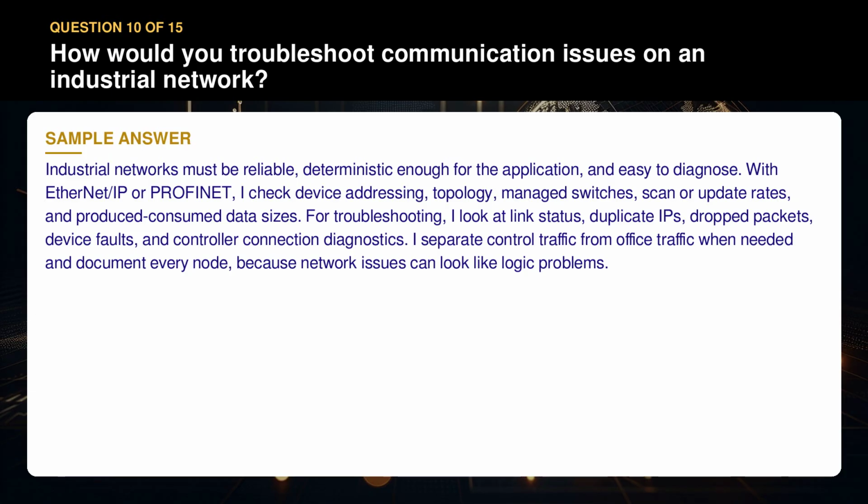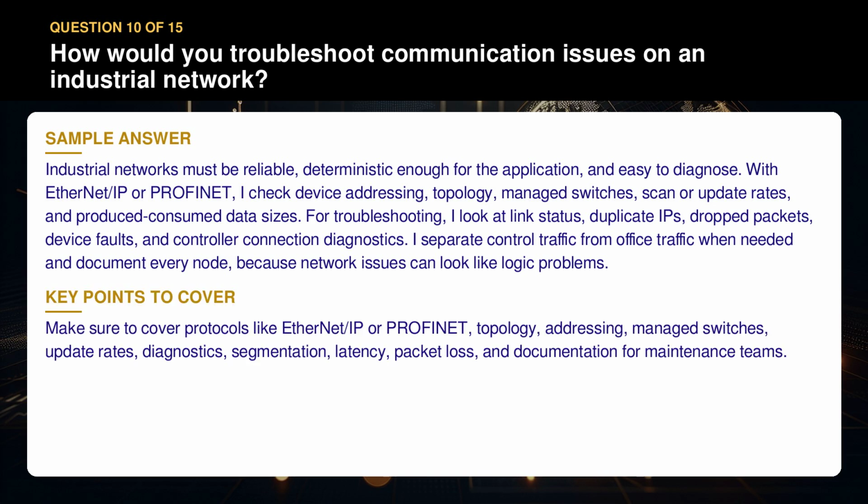I separate control traffic from office traffic when needed, and document every node, because network issues can look like logic problems. Make sure to cover protocols like Ethernet IP or Profinet, topology, addressing, managed switches, update rates, diagnostics, segmentation, latency, packet loss, and documentation for maintenance teams.